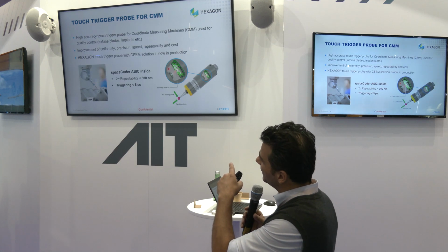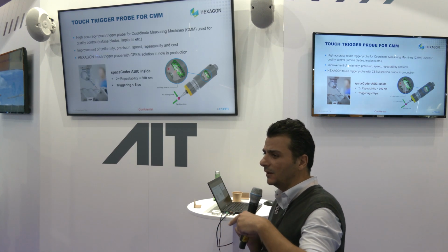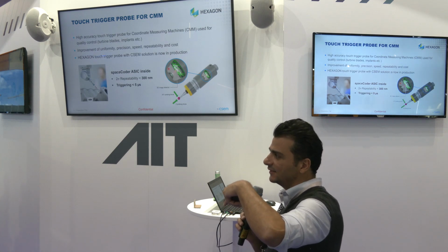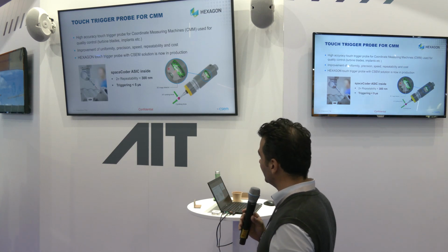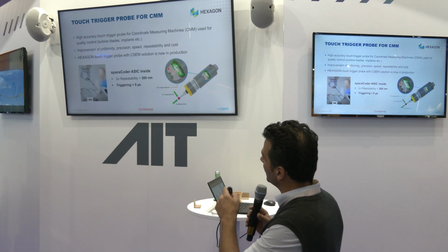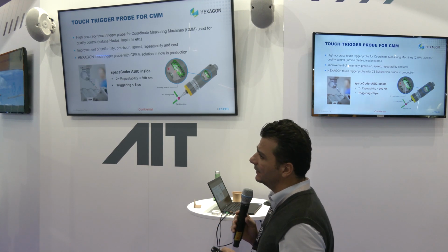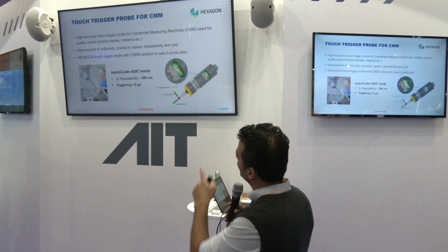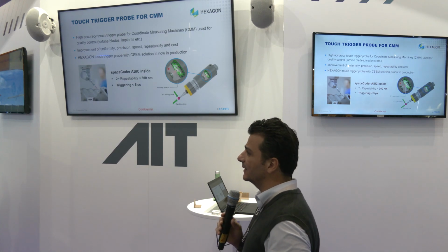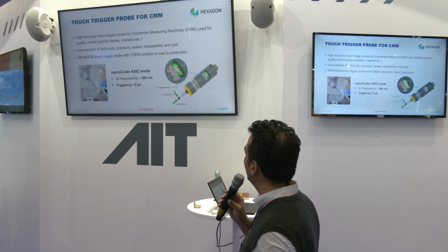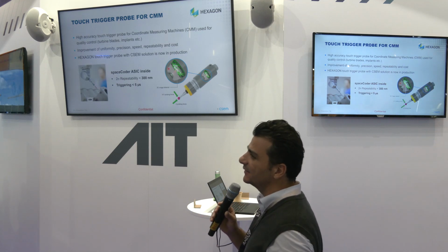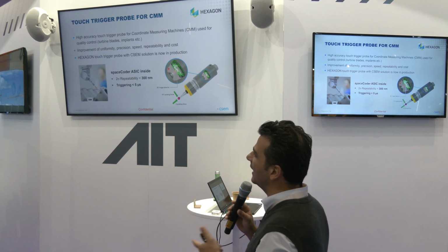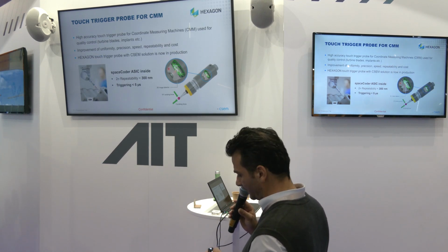This is very important, specifically when we are touching a contact surface and we want to be sure that the contact point is accurately sampled. All in all, the full system, including the mechanical assembly, is at 300 nanometers. And for that system to be able to reach the 5 microsecond cycle time, we had to develop a dedicated ASIC, which embeds both the imager and the processing required for it.